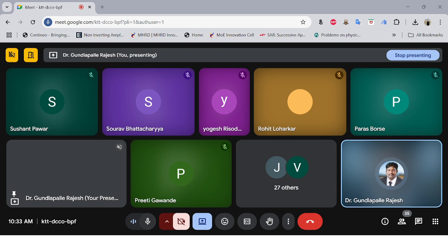Now UART is what you use for connecting a projector to a system. That is where you find your UART. You call it RS232, but basically they are UART and USART, with transmission and receiving lines and no clock line, and it uses a baud rate.